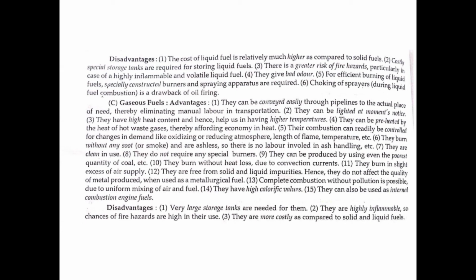Now we study the gaseous fuels, and their advantages are they can be controlled easily through a pipeline to the actual place of need, thereby eliminating manual labor in transportation. They can be ignited at a moment's notice. They have high heat content and hence help us in having higher temperature. They can be preheated by the heat of hot waste gases, therefore affording economy in heat.